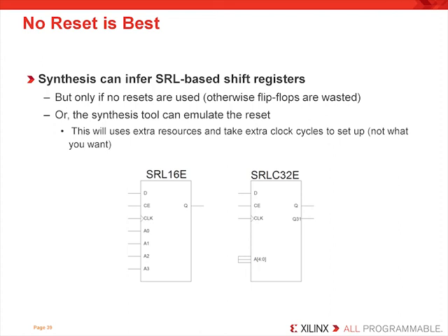Note that XST does not allow inference of the SRL when using a reset at all, so keep in mind that it's possible to build too much inference capability into a synthesis tool, and that you should always make sure you're inferring the dedicated hardware that you expect to get. Now note that this situation does not occur if you used a GSR. We're only really talking about the case when you're using a local reset.